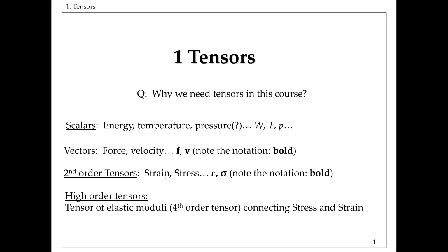A material can be very complicated, and if we apply stress in certain directions, you would expect from a complicated material that deformation will develop in other directions, or if you apply deformation, you expect stresses developing in other directions. Depending on the complexity of the materials, that could be possible, and mathematically that can be allowed through the fourth order tensor. So a fourth order tensor will allow us to connect all the components of stress to strain.